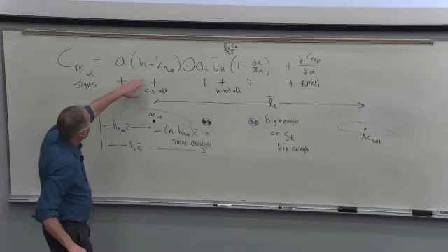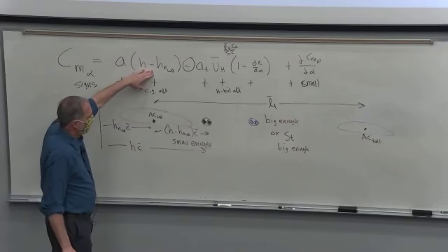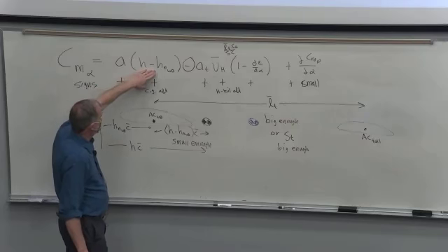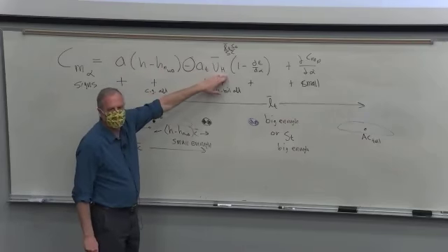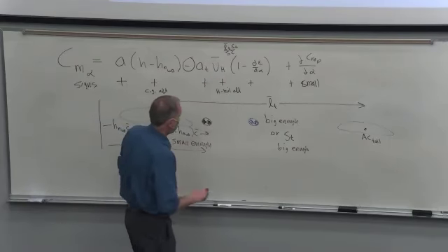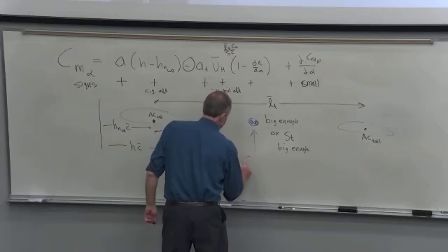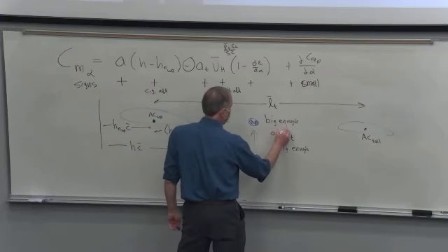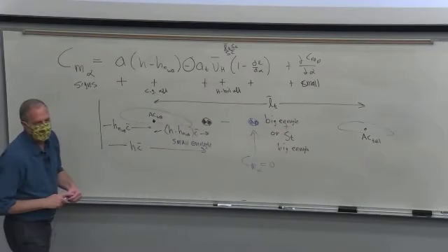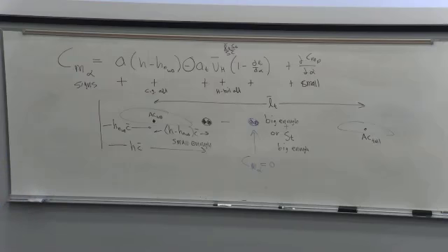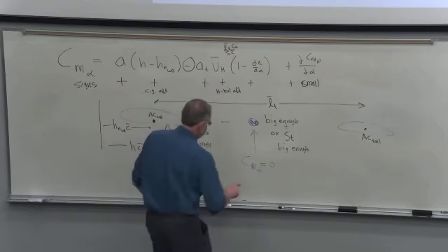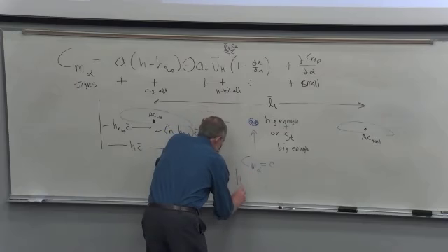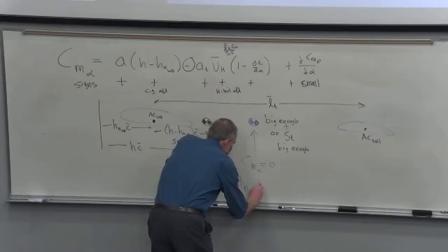If we make this distance bigger and bigger, it's going to eventually make this term bigger than this, and you're going to get a positive CM alpha. So in fact, there's a spot here where CM alpha switches from negative to positive. And we want to know where that is because we want to make sure that we don't load our airplane with cargo and people enough so that it shifts the CG back behind that point. And this thing, the point where CM alpha is 0, is called HN, and it's the neutral point.